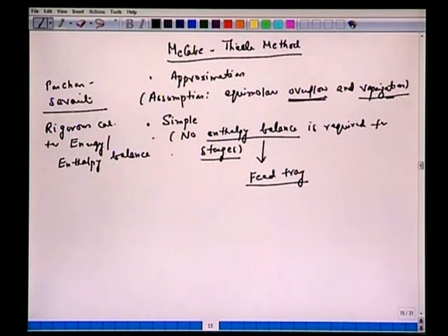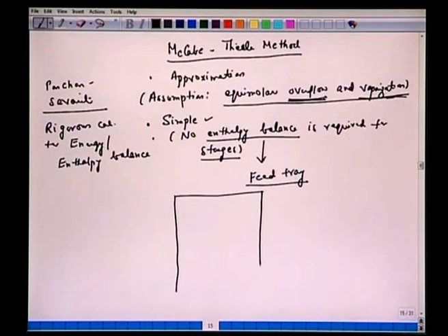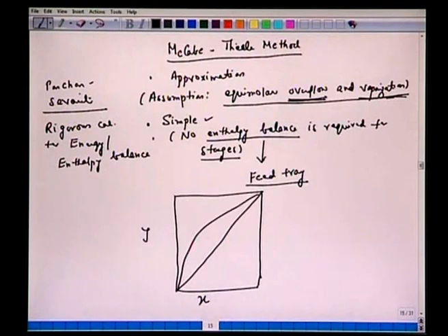So you can see that this method has, although very rigorous assumptions as it reads here, but it results in a very considerable simplicity. Okay. So essentially, all the time or most of the times we would be referring to this y versus x equilibrium diagram. So this is the foundation and the basis of your McCabe-Thiele method.